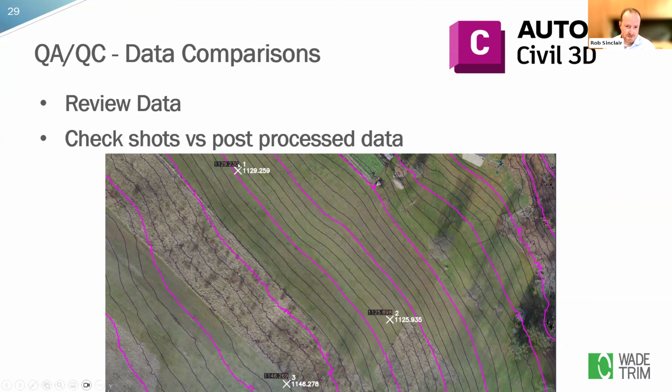You'd see this one is off by just over a hundredth. These ones are pretty close too. And this is a great way to identify, did we screw up and select the wrong coordinate system, the wrong unit of measure, any other thing that could go wrong. This is really where you can nail that down and make sure you have good quality data.